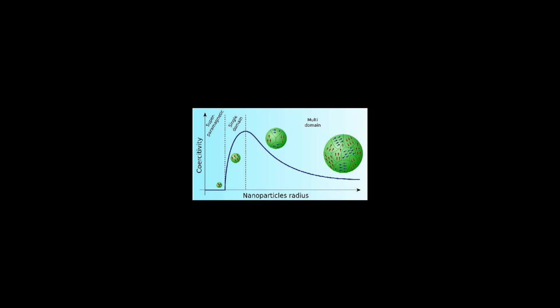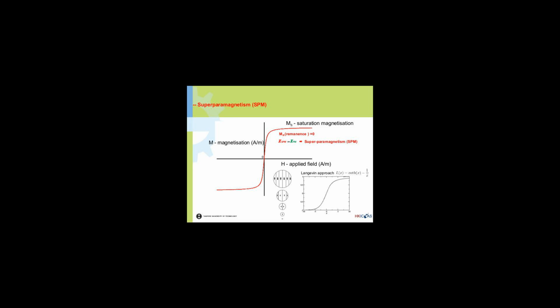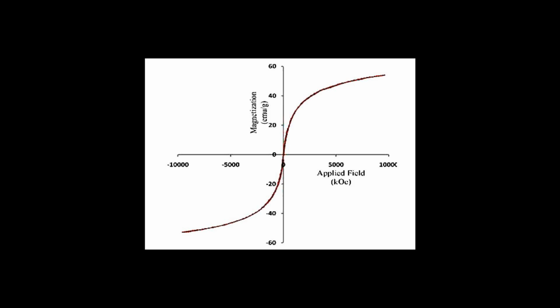1024 Gbit/in². Future hard disk technologies currently in development include heat-assisted magnetic recording, HAMR, which uses materials that are stable at much smaller sizes. They require heating before the magnetic orientation of a bit can be changed, and bit-patterned recording, BPR. In addition, magnetic recording technologies based on topological distortions of the magnetization, known as skyrmions, have been proposed.